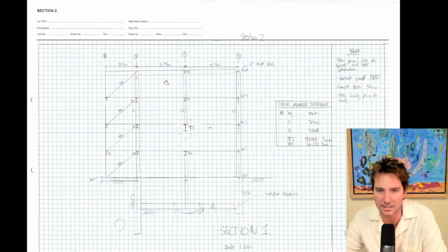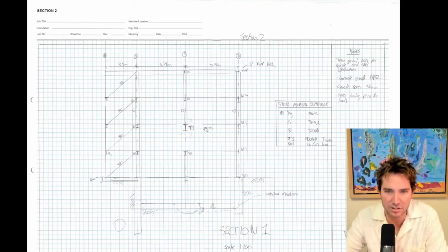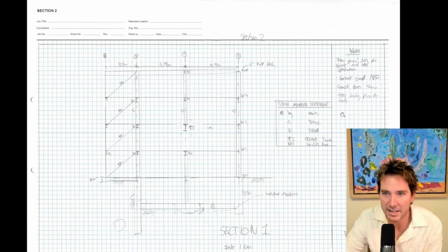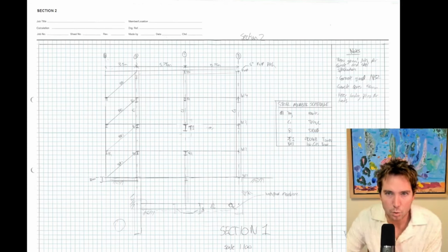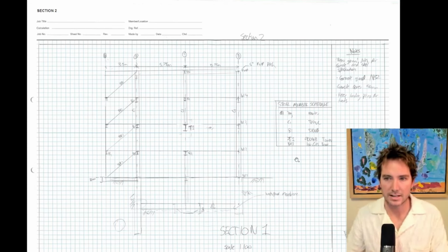Third drawing, I'm adding that section to capture. By this point of the exam, I learned to use a pencil, so you can see I rubbed some things out. That's something that I learned on the weekend. Here, again, I'm using steel member schedules where I'm labeling the columns, my diagonal bracing, showing my thickenings here, my D walls, got some general notes, and just a title block. So that's what I've got.